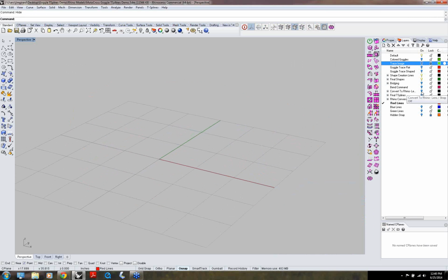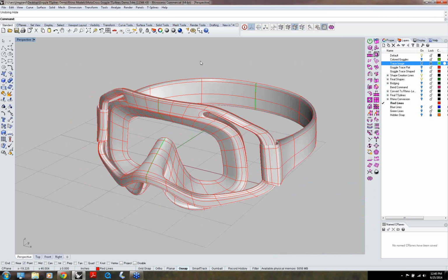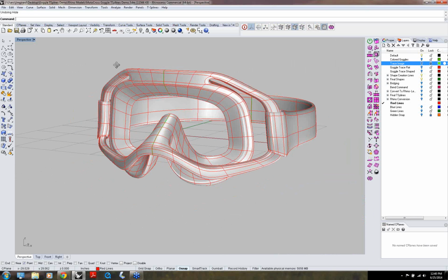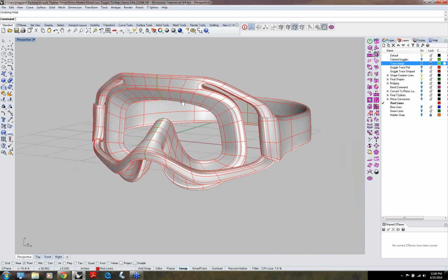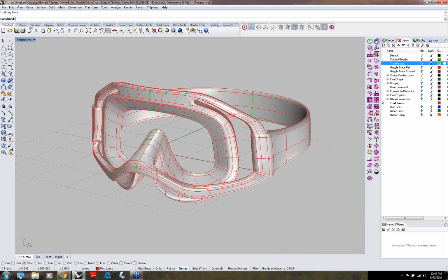And then oh, you know what? Once you've done this and you've got it where you want to, now you can convert it to a Rhino model. And that is done over here where it says convert to Rhino NURBS. Now, one thing I'd like to point out to you, if you look up at your command line, you have the opportunity to hit copy. And when you do that, it'll make a Rhino NURBS translation and also save your T-Splines model,